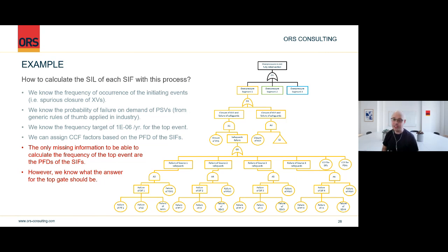You could also do reliability block diagrams of this, but fault tree to me is the way to go when we want to calculate probabilities of failure, especially because of what was said before. Fault tree also gives us minimal cut sets, and it lets us know what the most vulnerable part of the process is. So that's also good for fault tree.